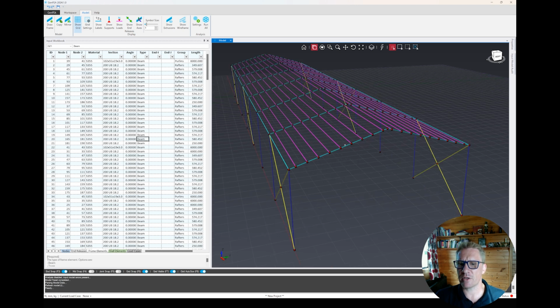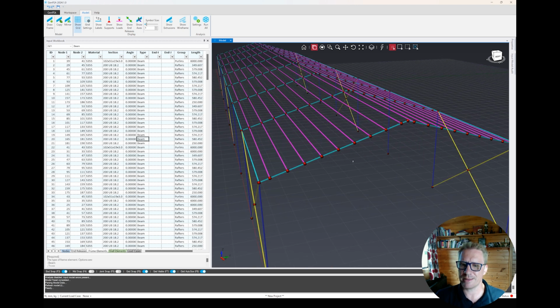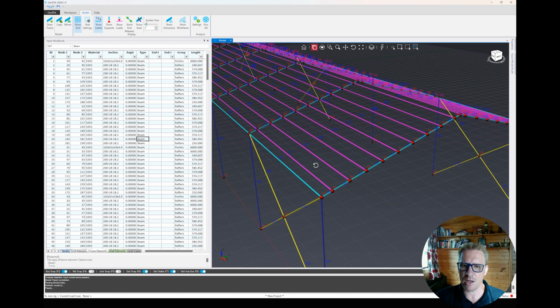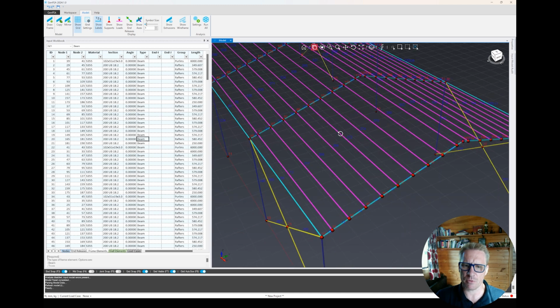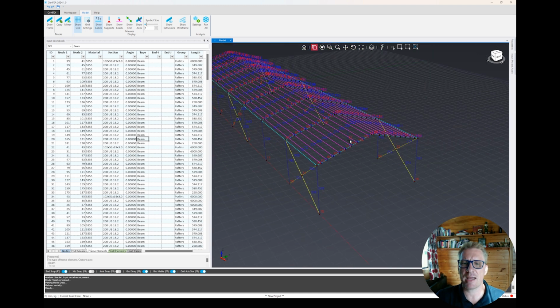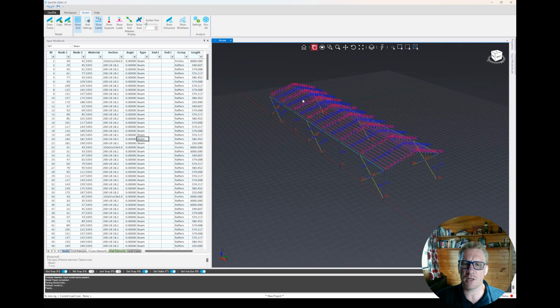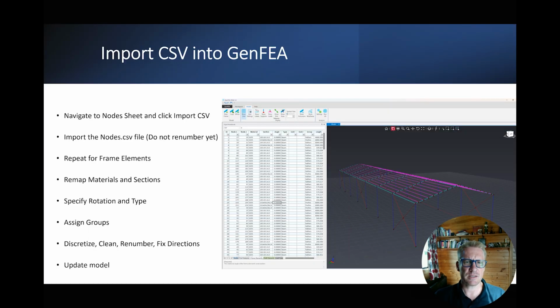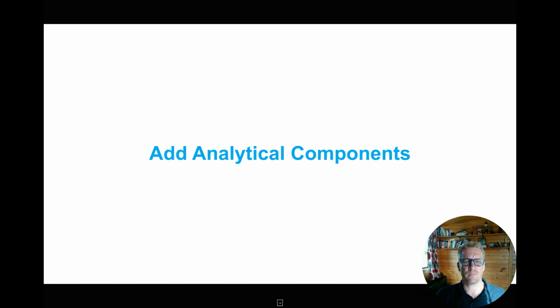But now you can see if I try to select the elements, they are highlighting and discretized across the model. And in fact, if we click on the show labels button here, it's going to help us to visually very quickly inspect and see. All the blue labels indicate beams, the red labels indicate nodes, and I don't see any duplications or anything wrong in the model. So far it looks pretty good. Let's head over to the next step.